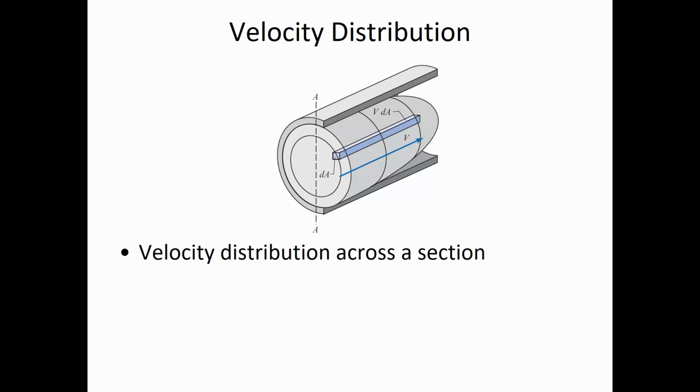So here at the center line, you're further away from the location where the friction is trying to slow down the movement of the water. If the water is moving to the right, then the pipe is pushing on the water to the left. The frictional resistance is always in the opposing direction of flow. So the water's moving to the right, and there are a lot of different velocities depending on where you are inside the pipe. The closer you are to the edge, the velocity decreases, and in fact, right here at the edge, the velocity is 0 because of the no-slip condition.